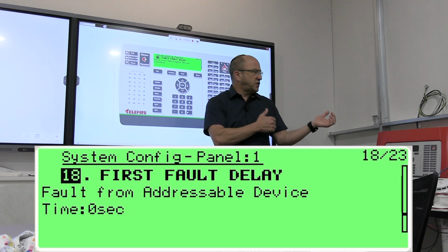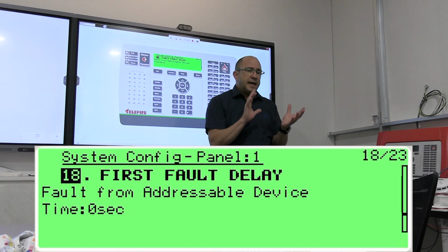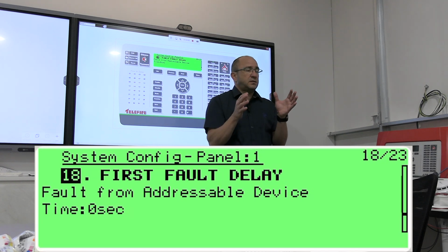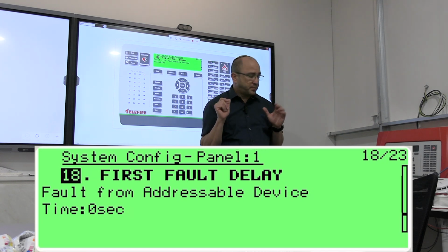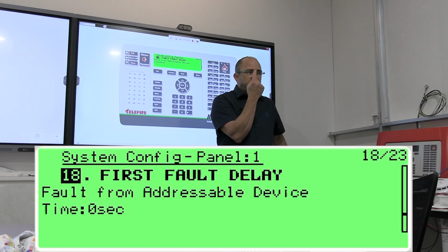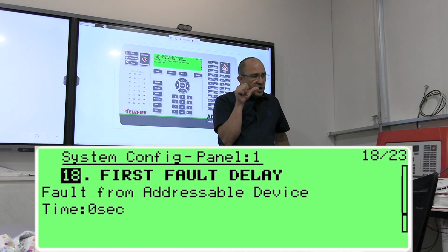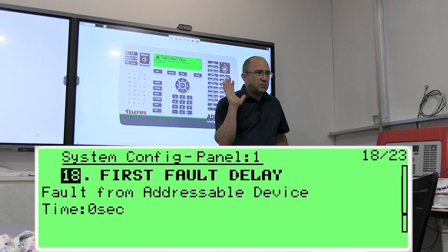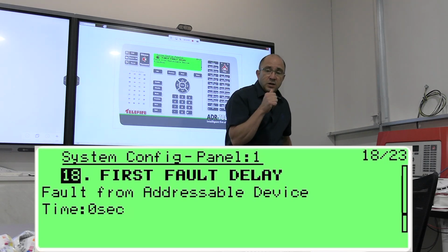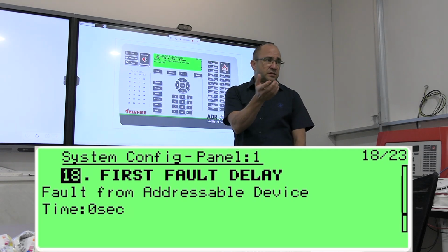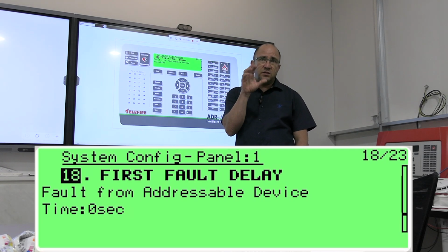It checks itself, it checks the system, it sees what's going on. And until everything's okay, it has a fault. Only after 40 seconds, it will say it's okay. So if you have only one of those devices, I promise you, after you do reset, you're going to get a fault for about 40 seconds.